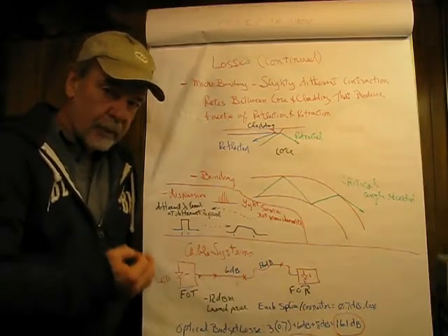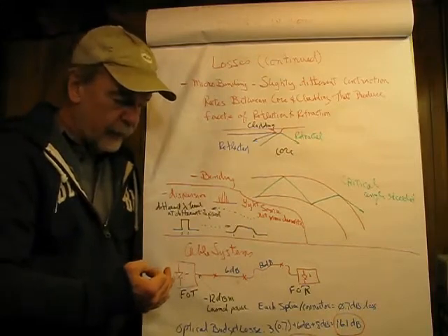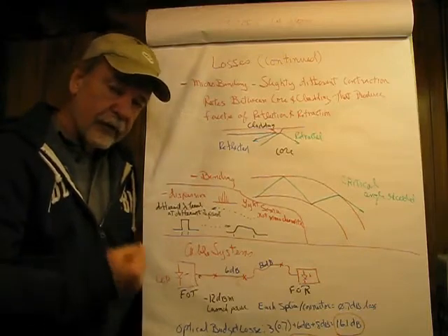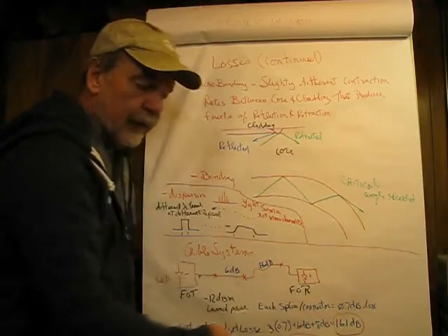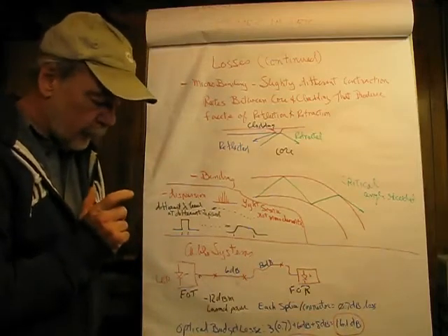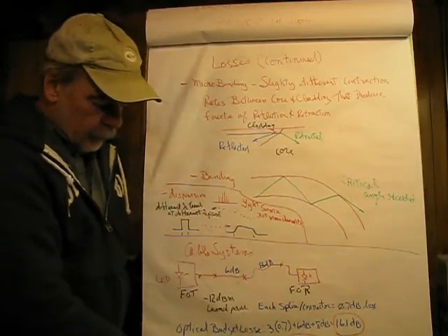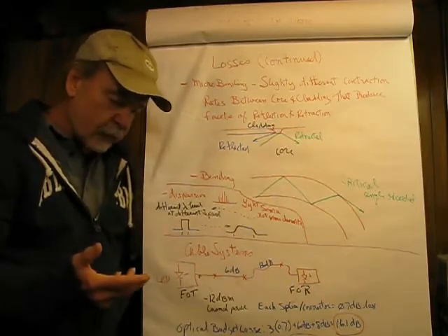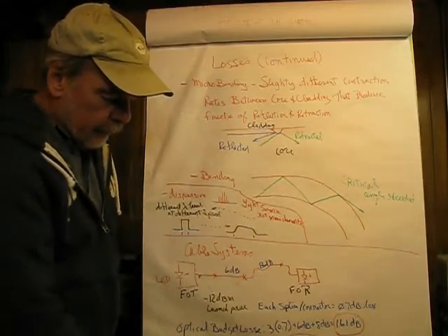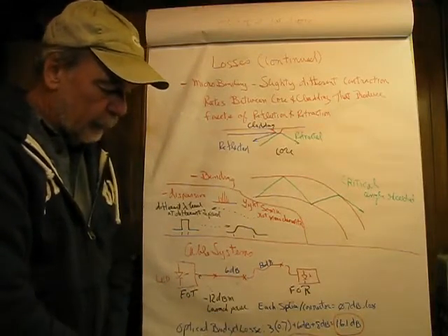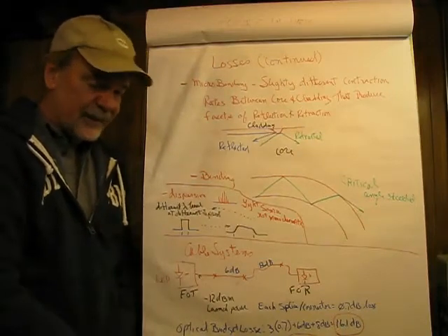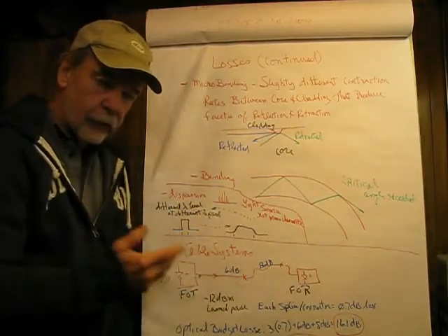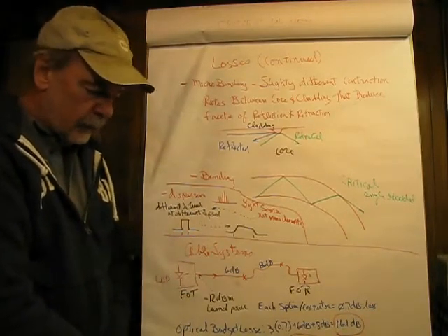Now the word loss means negative gain. So I could say that the gain of the fiber optic system is negative 16.1 dB. That is never used. It's always expressed as a positive number with the word loss in front of it. So the receive level then would be starting out with negative 12 dBm, and then subtracting from that the loss of our cable, which is 16.1 dB, gives us a receive level of negative 28.1 dBm, because this is a power. So you have to be careful of dBm versus dB. It's very incorrect to get them confused.